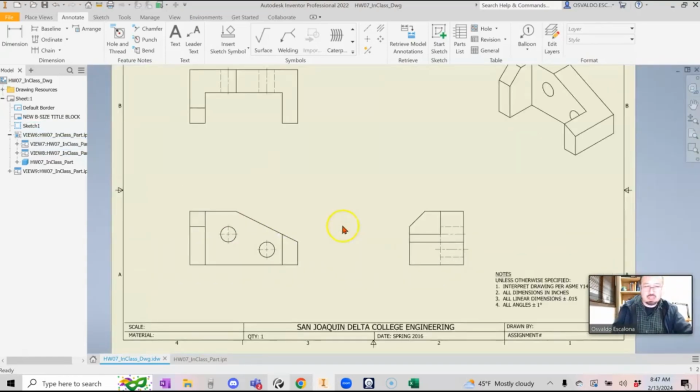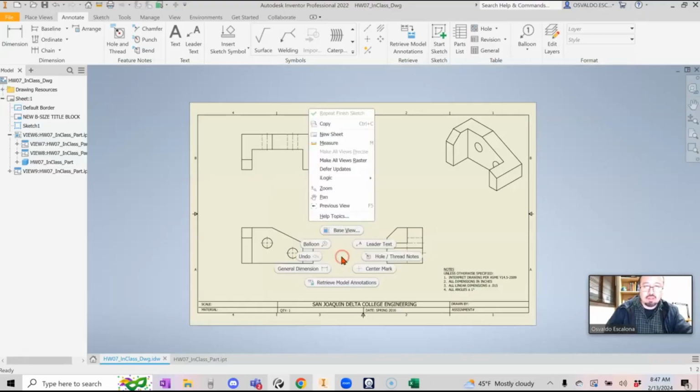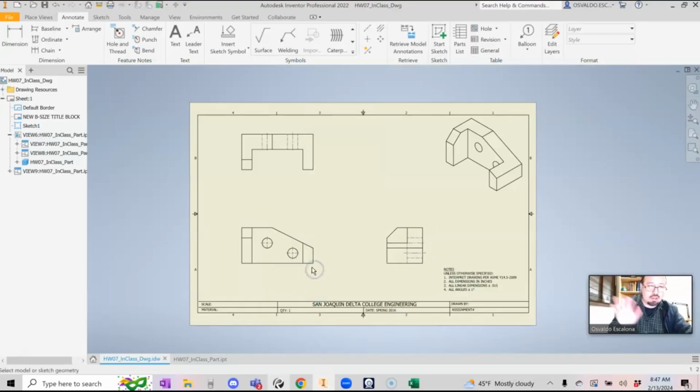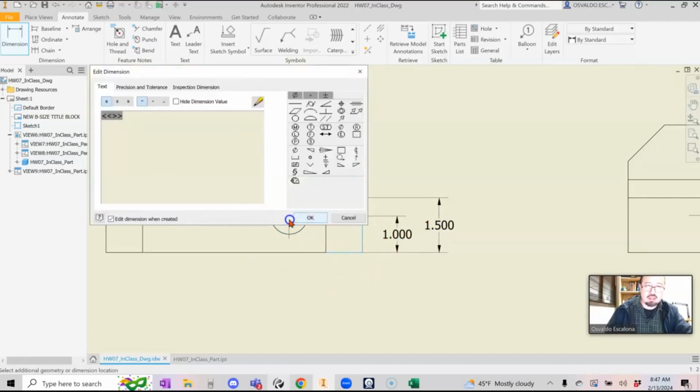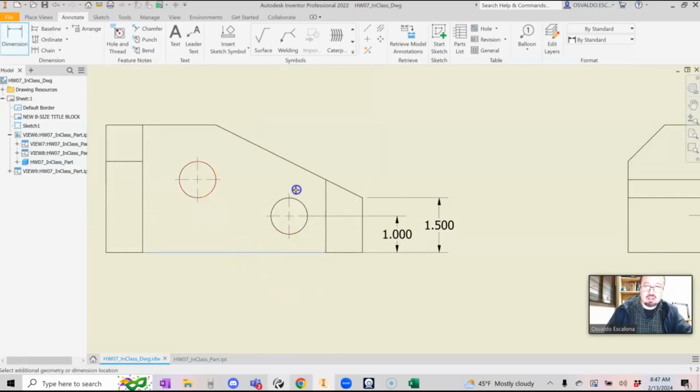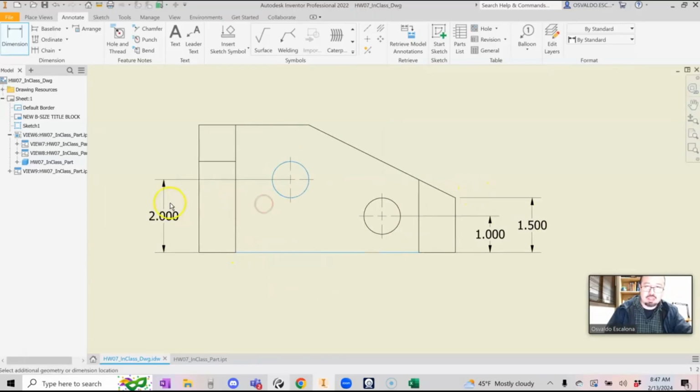And then I just got to measure the dimensions. So how do I get a dimension? Well, from the bottom, top. So the first thing from my bottom datum to the hole is that one. The next thing, click on there. The next thing is this one. That's the next feature. Say okay. I don't want to edit the dimension every time I put it, otherwise it's going to take forever. I'm going to make another one right there. Actually, let's put it on the opposite side.